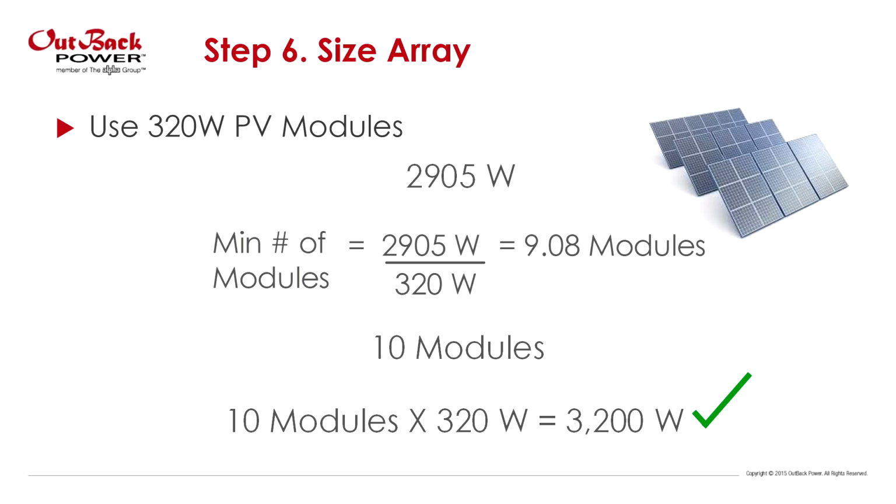This is for my grid tie installers. I said earlier that we're not going to go into module configuration, but I will say this. For most 80 amp, 150 volt charge controllers, you might just round up to 12 modules and go for a 4x3 configuration, because 10 modules is kind of an awkward number.